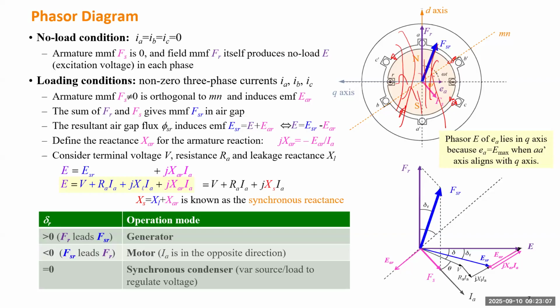But for a salient pole rotor generator, that can be different, because you can think about in the quadrature direction, there will be more air gap. So the more air gap, which means it's harder to build up the flux. If we're familiar with this formula in the electric circuit, we know the voltage is equal to current multiplied by resistance, right?